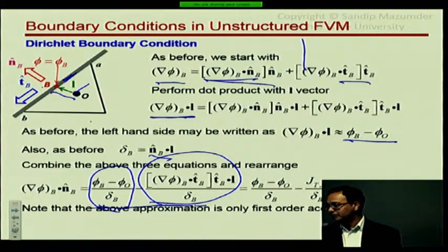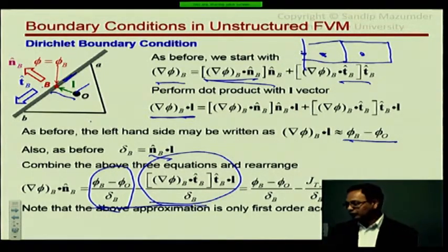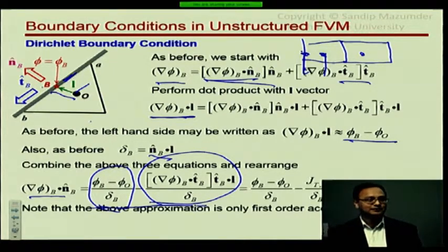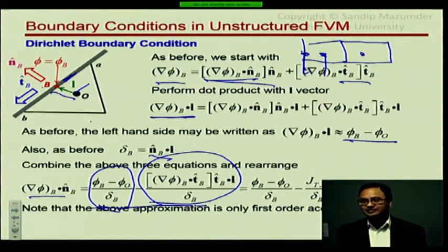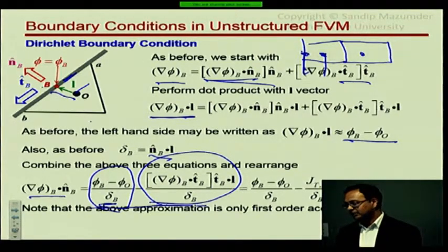This is kind of like a Cartesian mesh. Remember when we did boundary conditions in a Cartesian mesh, we did a Taylor series expansion of this about that and then this about that to derive a second order expression. Now we are simply saying the derivative at the boundary is nothing but this value minus this value divided by that distance, because we can't do those two-point nice Taylor series expansions anymore. So that's what is defaulted to. The boundary always sort of contaminates the solution a little bit. But of course, even for interior cells, you're not guaranteed second order in this case.